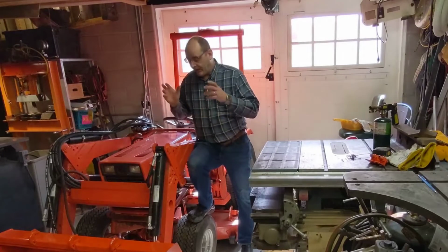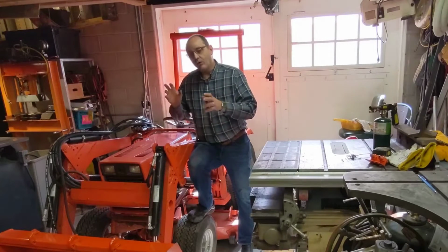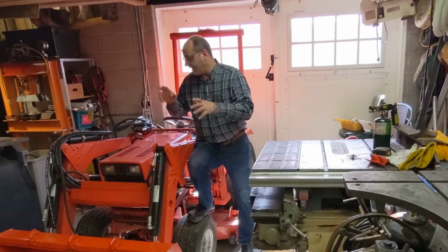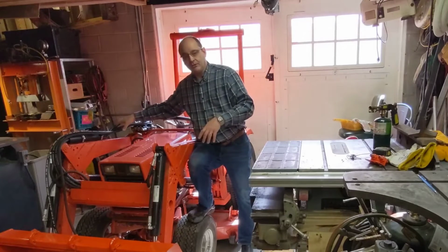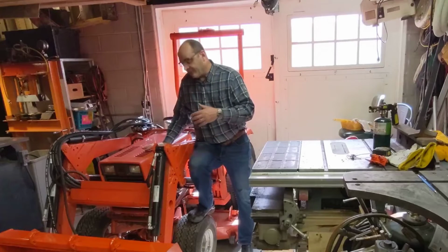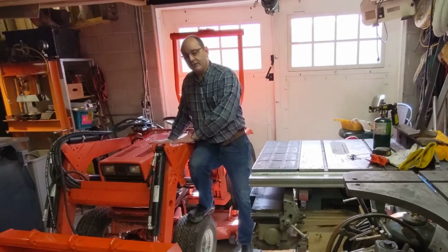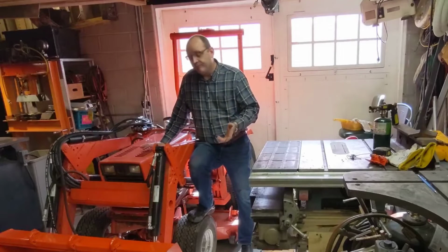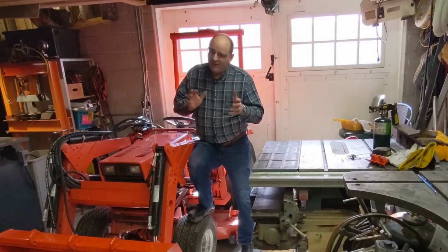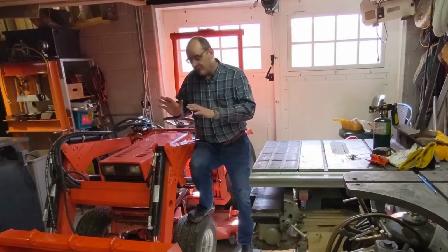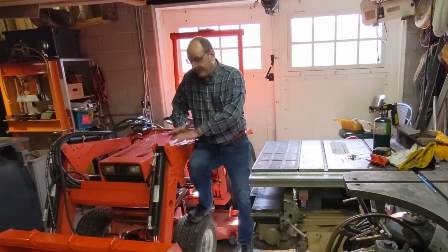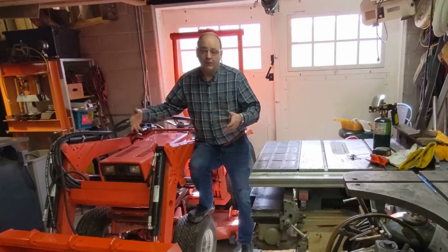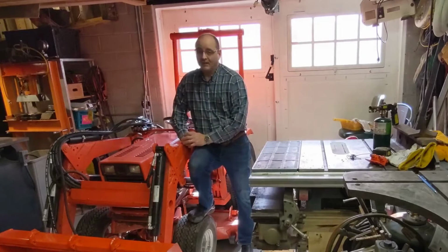When we put in a priority flow divider, we're going to be trying to balance the travel system needs of the tractor against the needs of the loader. Now in this case, if I reduce flow to the travel system, what it's going to represent is slower operating speed. And surely I can find a balance point that the machine still moves fast enough and still has enough flow to divert to the loader to make the loader useful. I think.